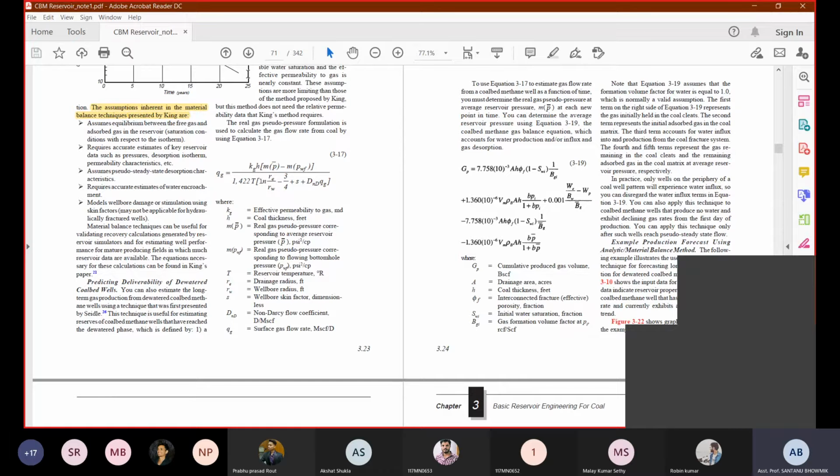So depending on the variation of the depth, the stresses will change and the pore pressure will change. If there are numerous fractures interconnected into a borehole, then when the water or the gas pressure goes into the side direction, it will again reduce the pressure and the production.